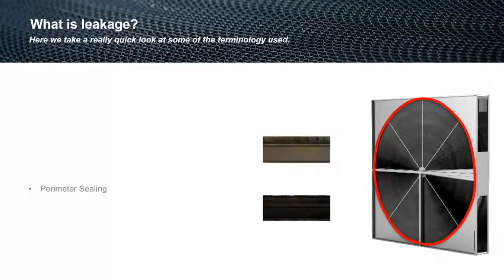So when we look at the perimeter seals, these are items that we need to check, and we should be checking during good maintenance procedures of the rotor itself, because it's a fixed component that's moving against a rotating component. So after time, these will wear down at some point. So it's an area in maintenance we should really focus on.